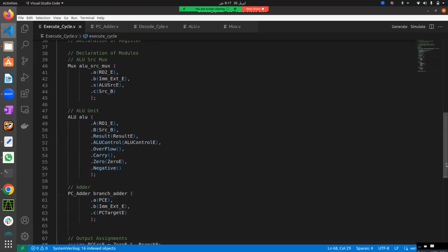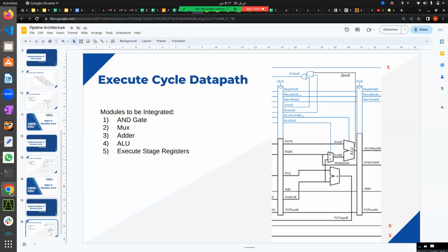All we have to do is declare the registers right now. You can see that write E signals are directly coming in and going out as the output port. Result has not been used anywhere, it's just an input and output. Mem write is an input and output. ALU control has been used, so we don't need that port. ALU source has been used, we don't need that.